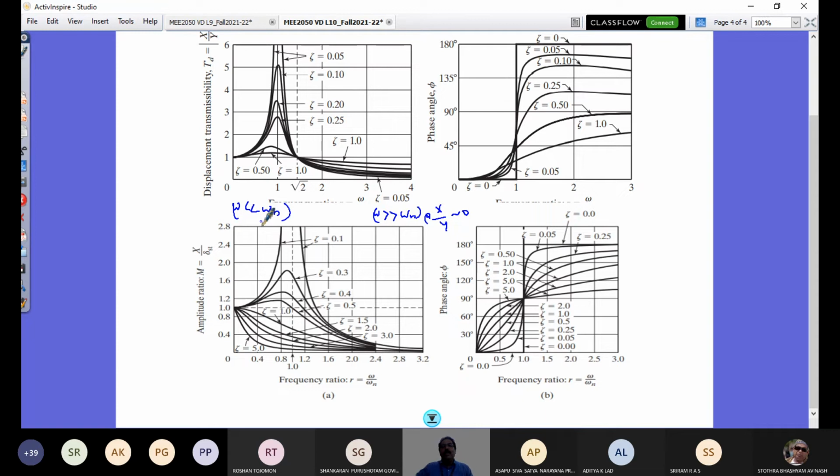That is why when it is on a wavy road, you go very slowly, right? Your natural frequency is 1 hertz. Your excitation frequency is not equal to 1 hertz; it's smaller than 1 hertz. Then the road profile is like that, and whatever your x is, that's going to be y. So your vehicle will just go with the wave like that. Both amplitudes would be the same. So whatever the amplitude of the road surface, the vehicle body also will have that amplitude of vibration.